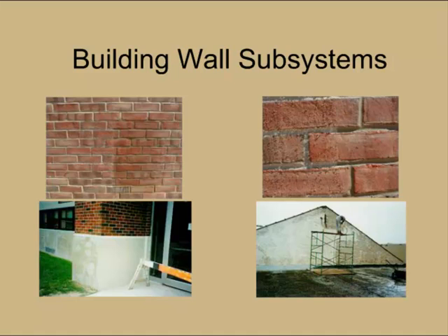It may actually darken the mortar and the brick a little bit initially, but when you look closer at the right-hand side there, you can see this area has been sprayed with water. The right-hand side has soaked in water, and on the left-hand side, it's a little hard to see, but there's beads of water standing on the surface.